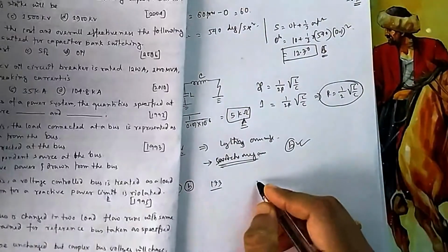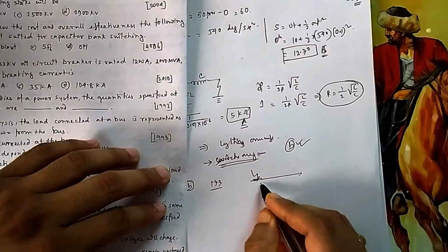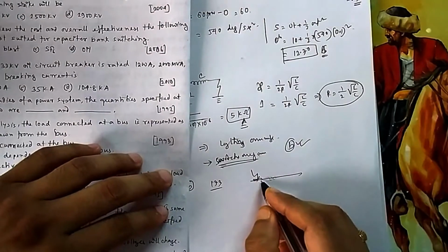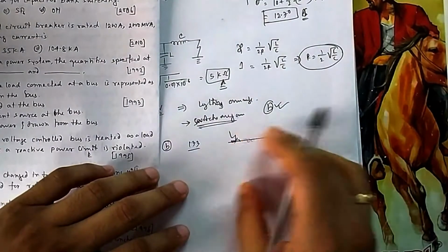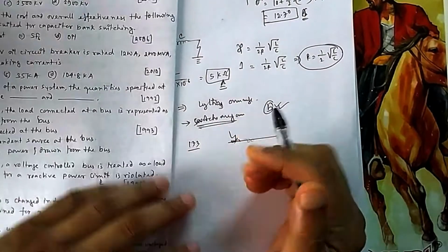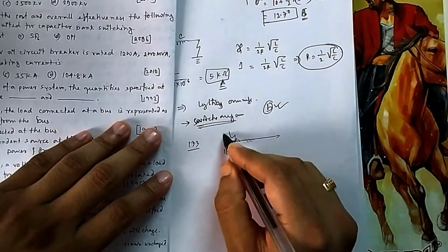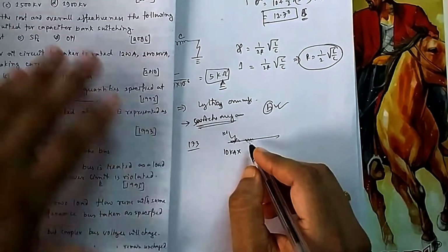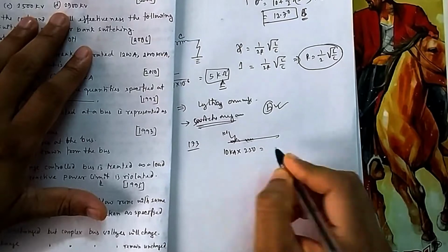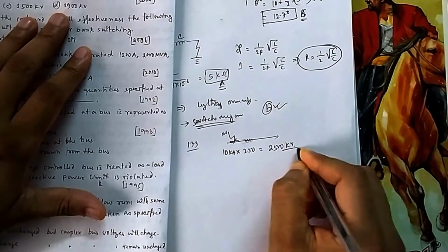Whenever the current strikes a transmission line, you see what the surge impedance is there, and on the basis of that you convert it into overvoltage. So if it is 10 kiloampere you are injecting, and you have a surge impedance of 250, this is the voltage that it will generate, that is 2500 kilovolt.